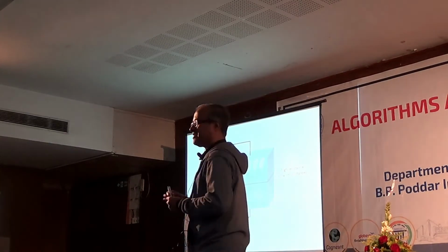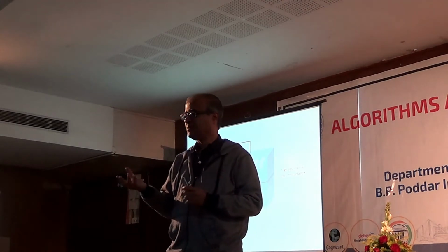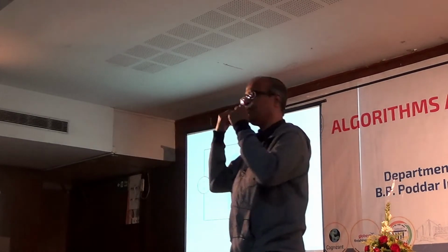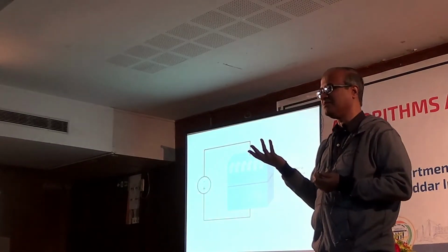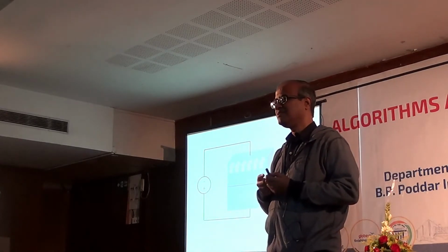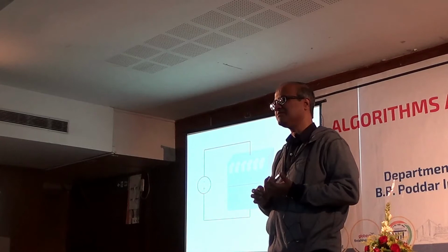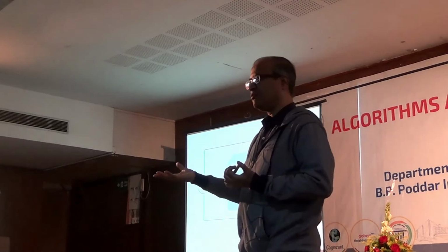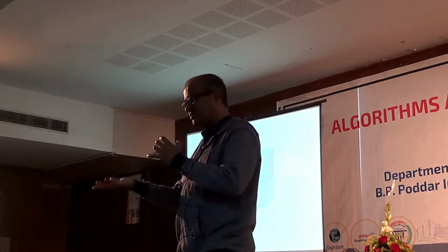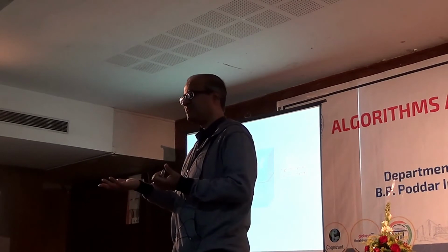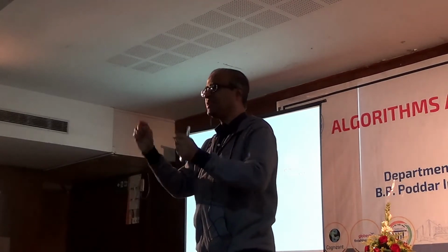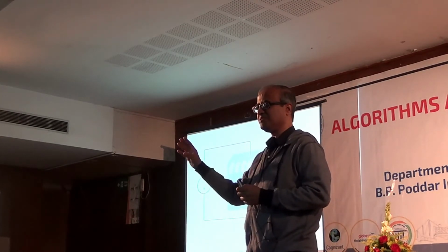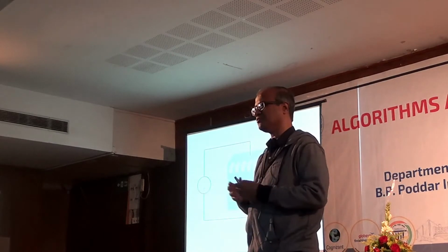So now you can think that I have a device whose resistance I can change by applying a voltage. Now if I withdraw the voltage, my resistance value is remembered. The device remembers the resistance. So can I use this device as a memory? In conventional MOS memories, we store the two states 0 and 1 typically either in the form of a flip-flop or as charge stored in a capacitor, static RAM versus dynamic RAM, as you know.